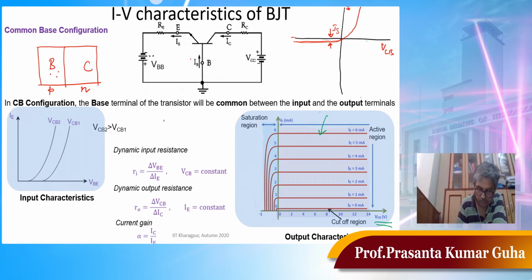Very few electrons are present because the base is lowly doped, and there are also very few holes here because those are minority carriers. If you connect them as reverse bias, so negative terminal to P and positive terminal to N, hardly any current flows, that is the reverse leakage current. You remember, we extensively discussed this in our diode discussion.